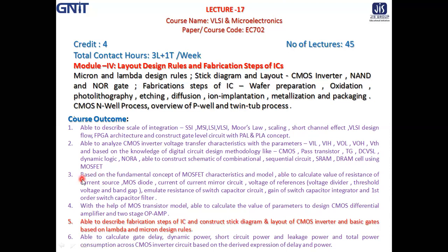Third, based on the fundamental concepts of MOSFET characteristics and models, to be able to calculate the value of the resistance of the current source, MOS diode, current of the current mirror circuit, voltage references such as the voltage divider, threshold voltage, then the band gap, and the emulated resistance of the switched capacitor circuit, gain of the switched capacitor integrator, and first order switched capacitor filter.